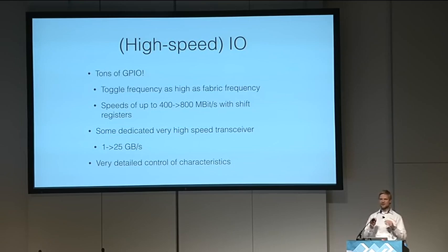And you also have very precise control of the signal. So you can, for example, say, okay, I want this pin to be 3.3 volt, and I want this one to be 1.8 volt. And you can say there should be a pull up, there should be a pull down, and you can also say that the drive strength, which is used for creating the edge, should be not so high, like 1 milliampere or like 8 milliamps. You can really define how you want the signal to be.